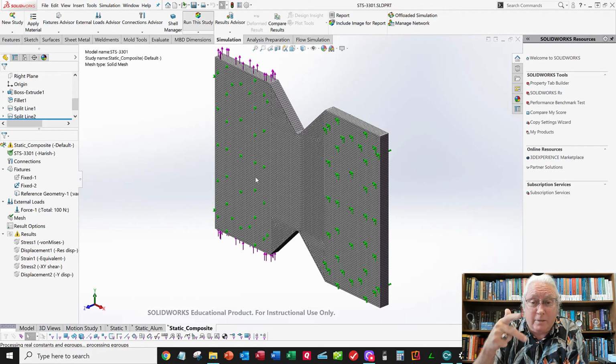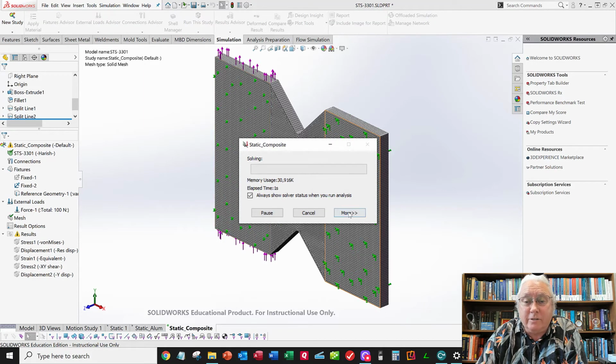Go watch that video if you missed it. It's got a lot of good stuff in there. Probably more than half of it's actually good, true. But anyway, they've got the compliance matrix, and then we do an inversion. We invert that gigantic matrix, and we get the stiffness matrix, and that's what it uses here. So it's got to invert these huge matrices, and they're thousands and thousands of elements.